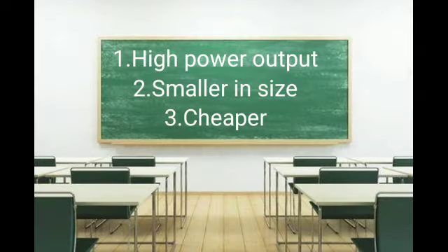Next topic is advantages of three-phase alternator. First one, for a given dimension of the generator, three-phase machine produces higher power output than a single-phase machine. Second one, for the same capacity, three-phase alternator is smaller in size when compared to single-phase alternator. Third one, three-phase transmission system is cheaper. A relatively thinner wire is sufficient for transmission of three-phase power.